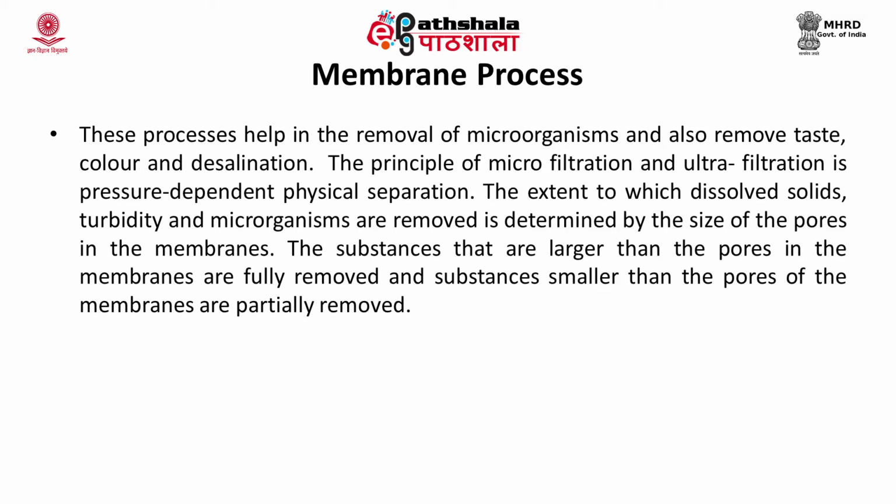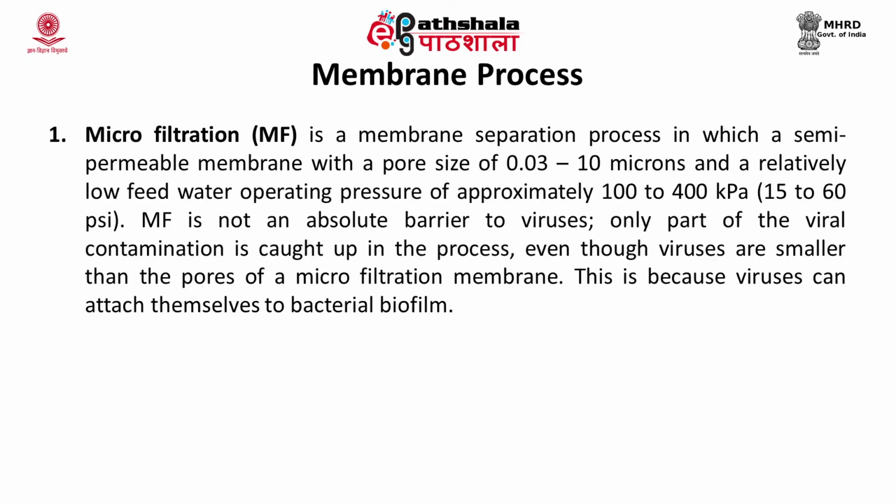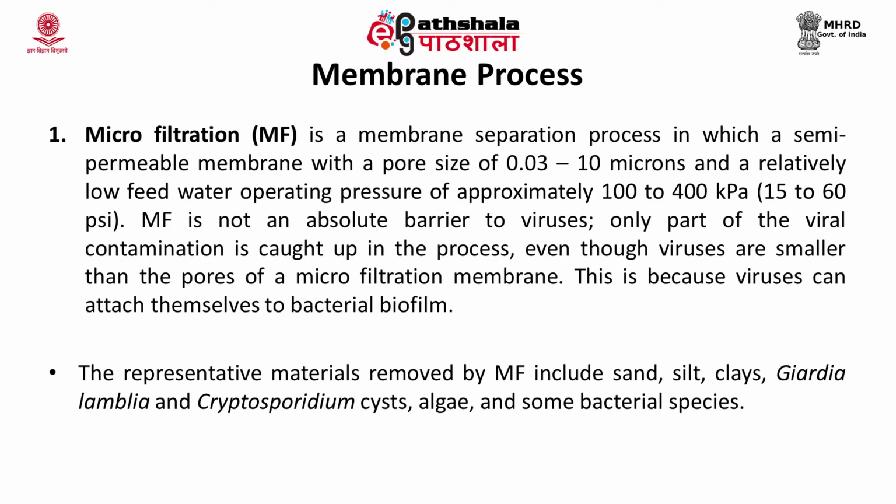These processes help in the removal of microorganisms. The extent to which dissolved solids, turbidity and microorganisms are removed from the water depends upon the size of the pores in the membrane. The substances that are larger than the pores in the membrane are fully removed, and the substances which are smaller than the pores of the membrane are partially removed, depending upon the construction of the membrane layer.